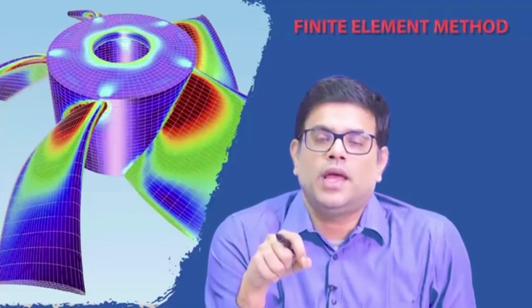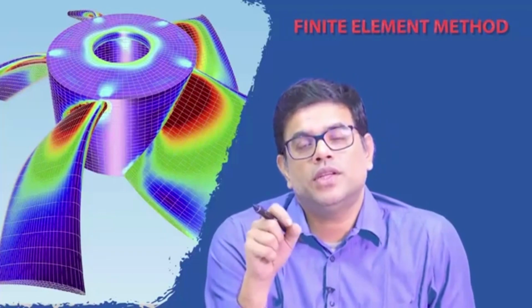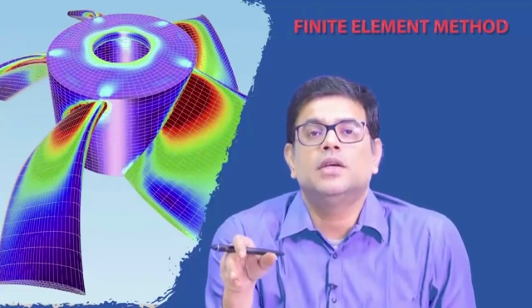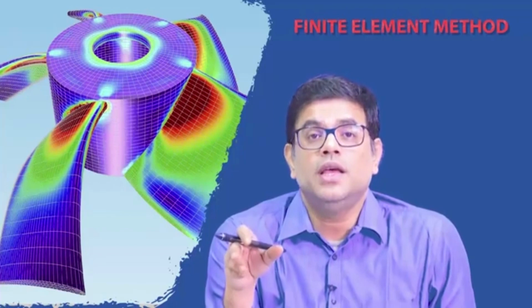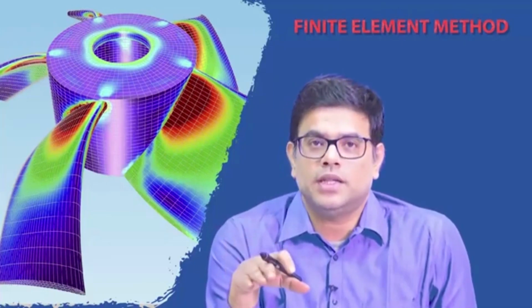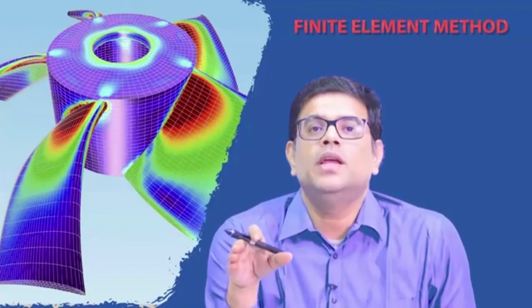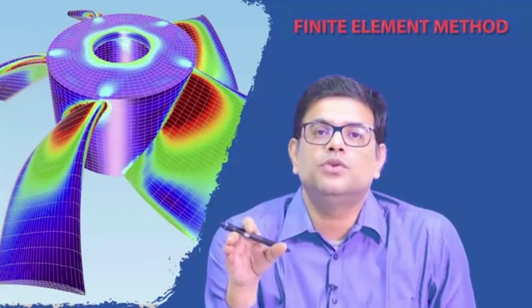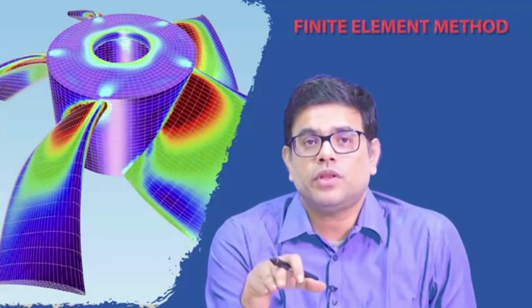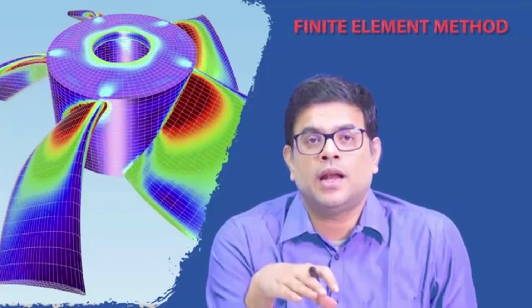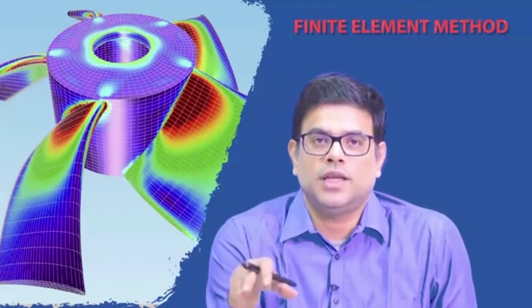Now, in another way we can view it like this: weighted residual methods are a kind of error orthogonalization, whereas the Rayleigh-Ritz methods can be thought of as energy minimization. In the structural mechanics problems that we will be dealing with here, the weighted residual methods and the Galerkin methods are mostly equal. We will obviously be doing integration by parts, and the Galerkin weighted formulation and the Rayleigh-Ritz formulation are the same for the cases we will study.